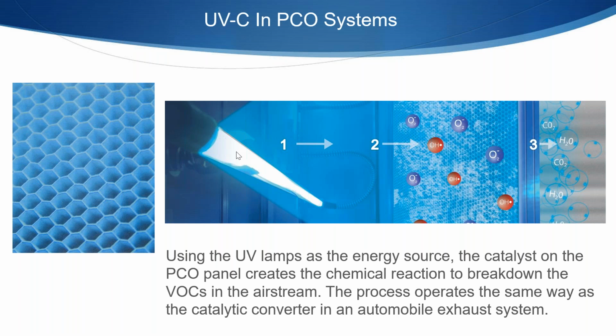If you have other needs in addition, like VOC mitigation and odor control, then this type of technology, ionization, photocatalytic oxidation, these types of technologies can be very effective at VOC mitigation and odor control, but the UV portion of it is the part that's actually inactivating the pathogen.